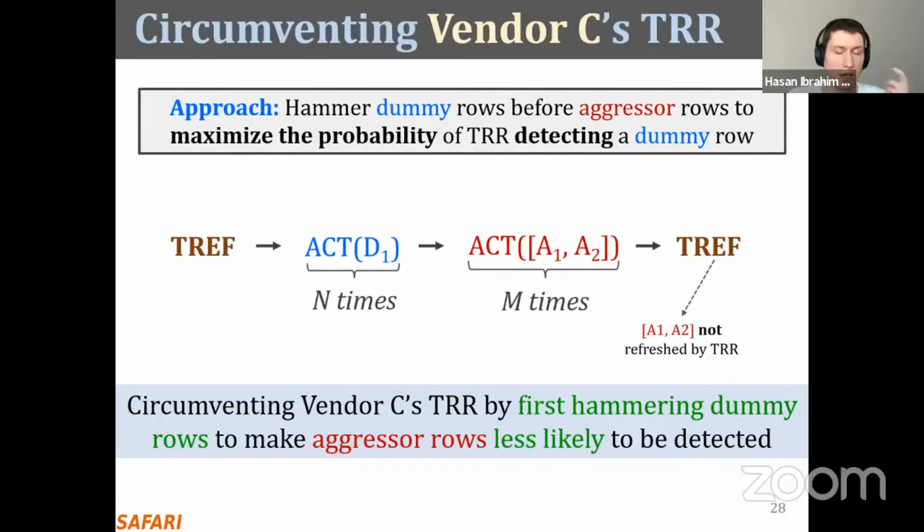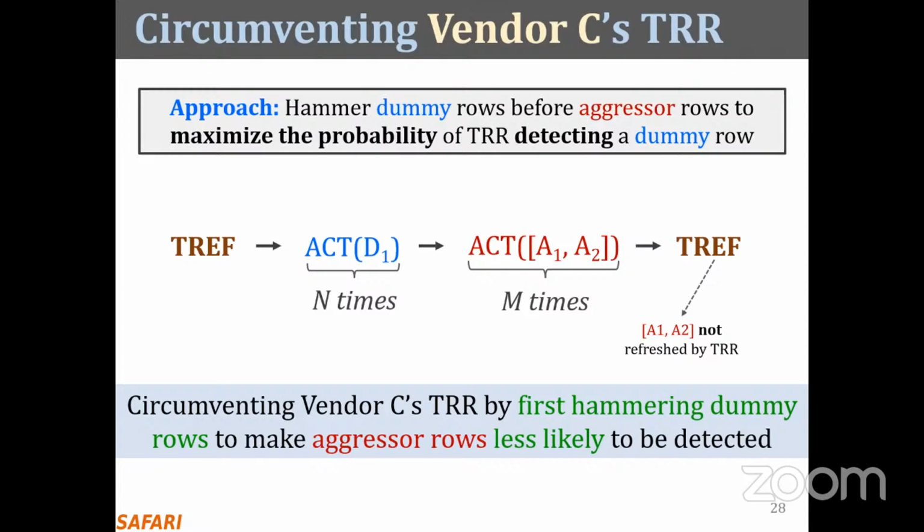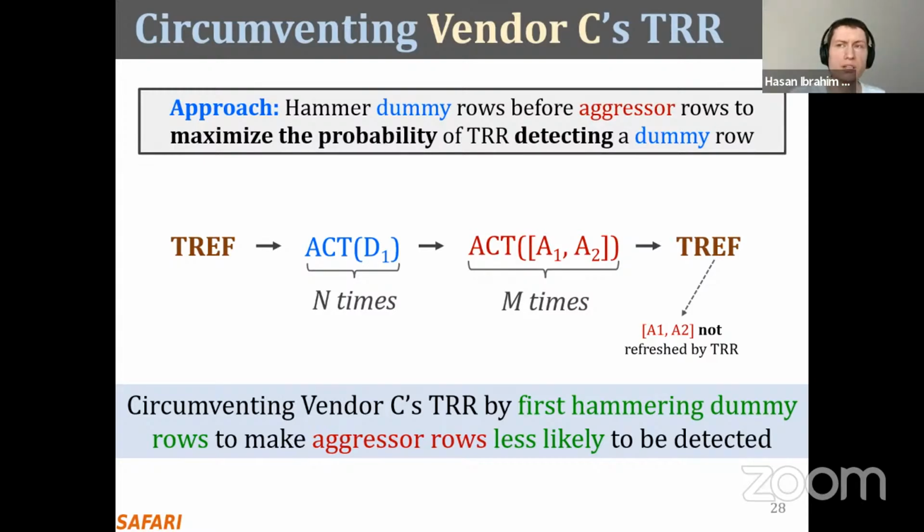Yeah, so in that table, actually, HC first, the hammer count, is just the minimum hammer count without any TRR, without any protection. So TRR is not considered. It is really an experiment we did to find out what is the vulnerability level of the DRAM rows without any protection.